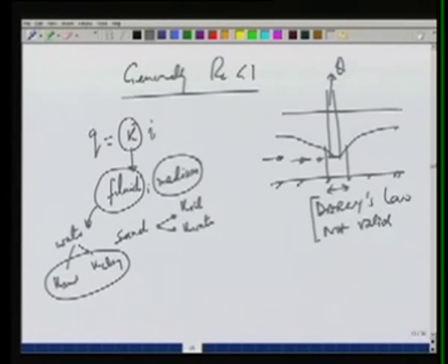We will see a little later that we can partition this into two parts, an intrinsic permeability K, and a term which will only depend on the fluid. So we will do this next time, using Darcy's law to derive the continuity equation. So in today's lecture we have seen what is groundwater, what the basic law, Darcy's law, is which governs the flow through the groundwater, and what should be kept in mind while applying Darcy's law. We have also seen different kinds of formations in terms of their water bearing capacity and water transmitting capacity, and in the next lecture we will derive the continuity equation for different kinds of aquifers.